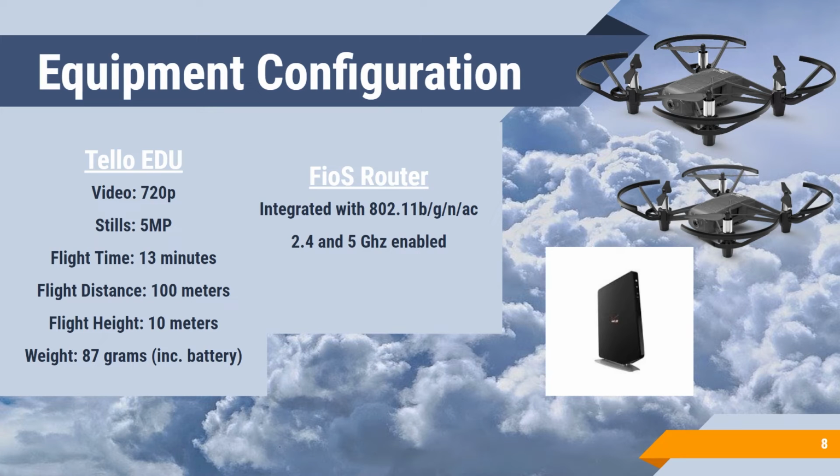So, our equipment configuration. Again, as Mahesh mentioned briefly, there is a difference between the traditional Tello drones that we've been using in our class thus far and the Tello EDU drones. The primary difference is that the drones we've been using in class are only capable of being used in what's known as station mode. Station mode is essentially where the drone will act as a station. It produces its own Wi-Fi network, which you then connect to issue commands. Alternatively, the Tello EDU drone has the station mode capability, but also has an access point mode. The access point essentially allows the drone to function as a client and connect to an external router.